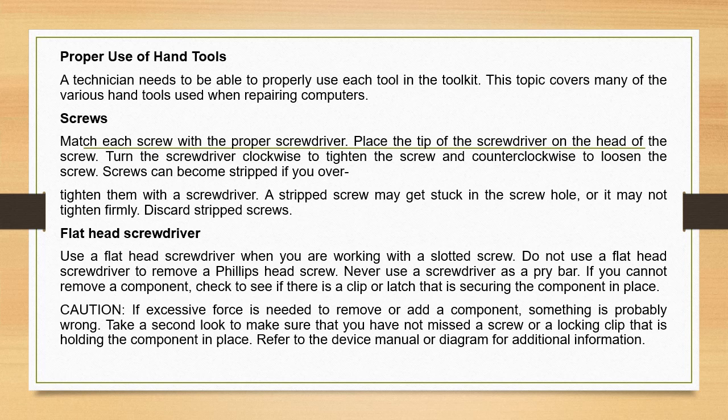The flat screwdriver. Use a flat screwdriver when you are working with a slotted screw. Do not use a flat head screwdriver to remove a Phillips head screw. Never use a screwdriver as a pry bar.